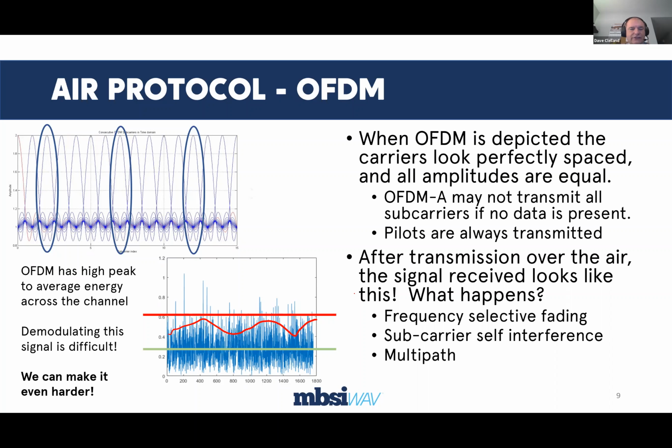Also, we have a situation where this carrier and this carrier, for example, as they're traveling through this free space here, they can interfere with each other. So right here in this plot, of course, they're all nicely sitting in the null of the second harmonic of each one of the carriers. The peak that we see here is primary. The peak that we see here is right there. So if this were the primary, this peak is the third harmonic. This peak would be the fifth harmonic of the carrier.